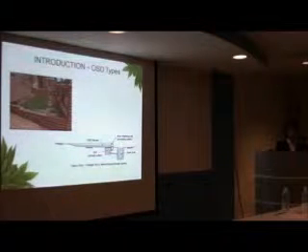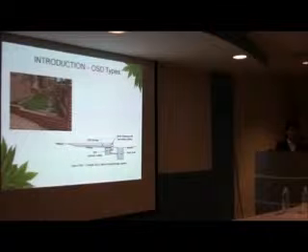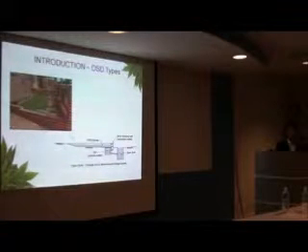This one, a little drop here. This one is a secondary outlet. If this above ground OSD overflows, water will overflow from here and then flow down to the roadside drain. This is an above ground OSD.